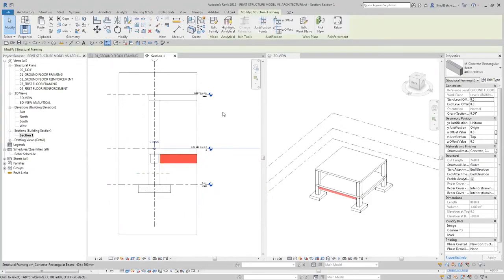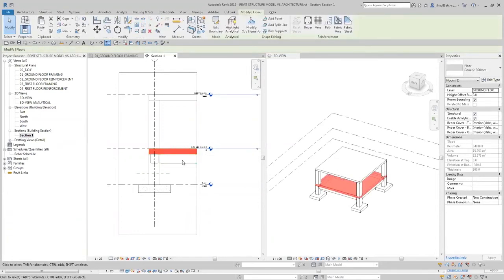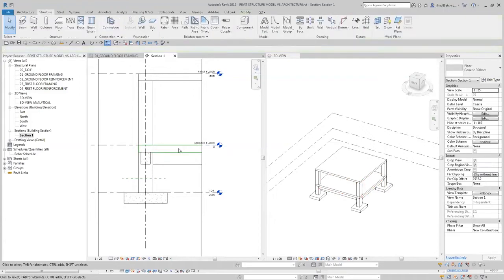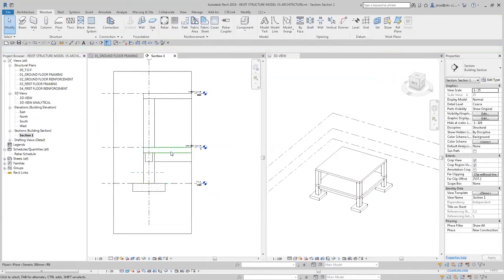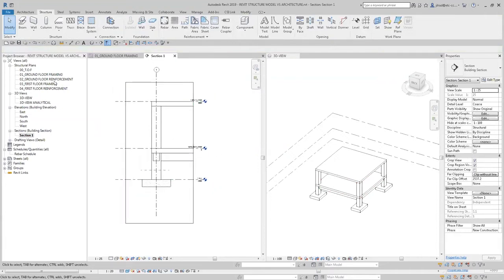So, by selecting a specific element as seen here, Revit will guide us in what to do, meaning that it will tell us that this specific element is a beam, so we can use rebar, for example. After selecting the slab, Revit will give us notice that we should either use rebar, area reinforcement, or various other options. We will learn in a bit why each selection is met with different options.